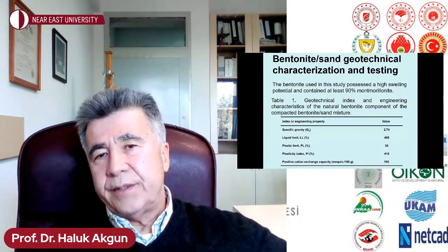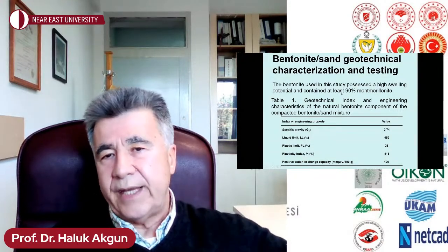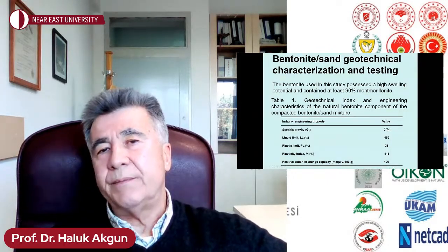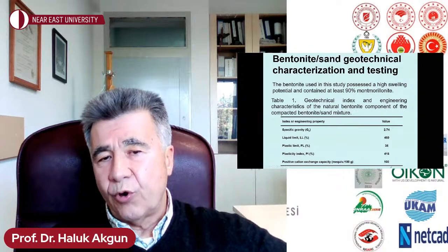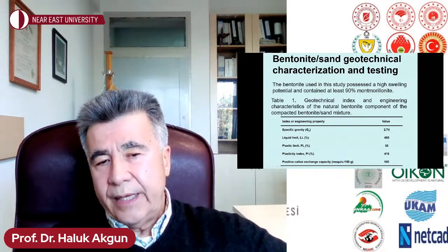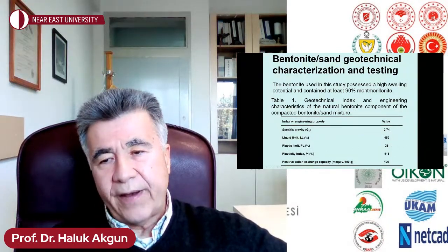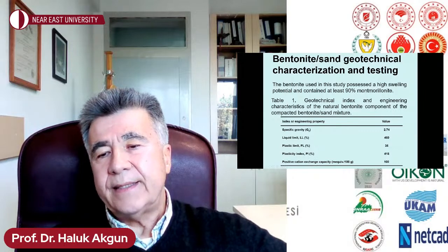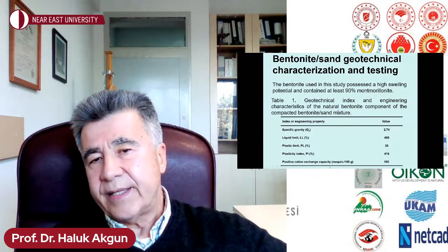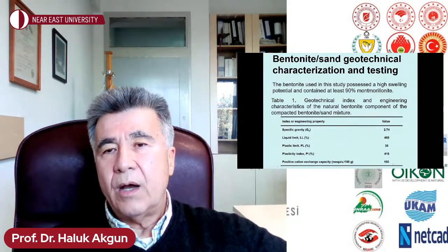We studied the geotechnical properties of this bentonite. It contained at least 90% montmorillonite, and these are the geotechnical properties that we have determined. Specific gravity 2.74, liquid limit 450%, plastic limit 35%, plasticity index 415%, and positive cation exchange capacity in milliequivalents per 100 grams was about 100.